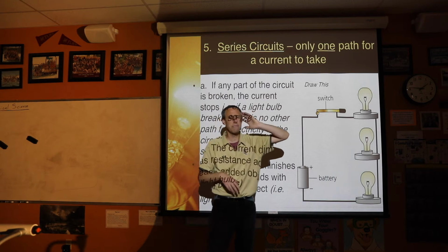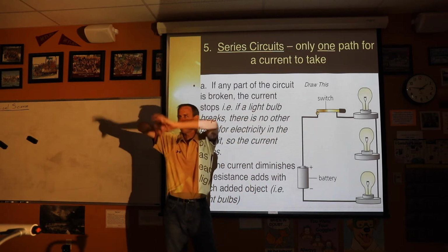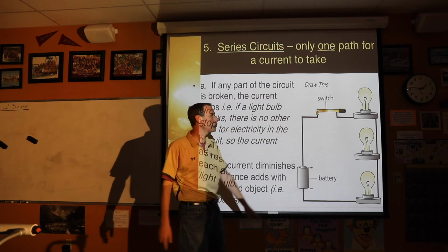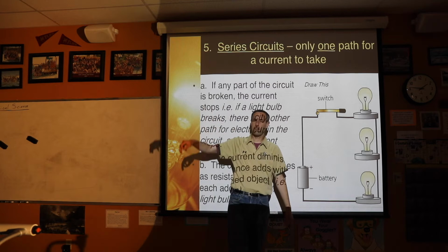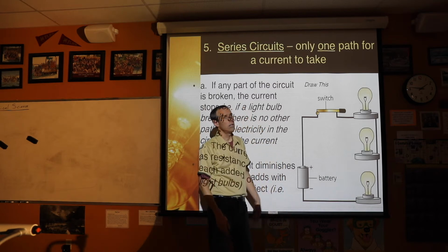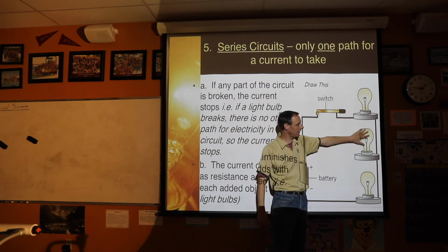But I have to sit there in my mind and go, when I bring this wire over, and then daisy chain it to the next ceiling fan, and that one to the next ceiling fan, I have to make sure I don't accidentally wire it in series. Because otherwise, all 3 ceiling fans would have to be on, and they would all be slower. The first one would get the most electricity, and then less and less.